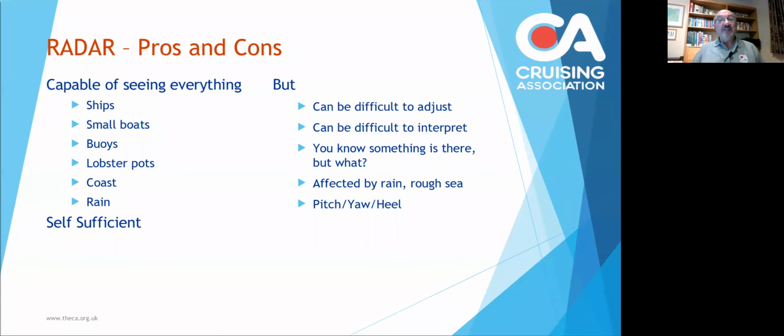And then lastly, there is the effects that you get on a small boat. If you're heeling a lot, for example, then it may well be that objects to the side cannot be seen. Most radars have a typical angle of view of about 20 degrees. And similarly, if your boat is pitching up and down, then again, it may miss particular objects if at that particular moment you're pointing upwards more than 20 degrees.